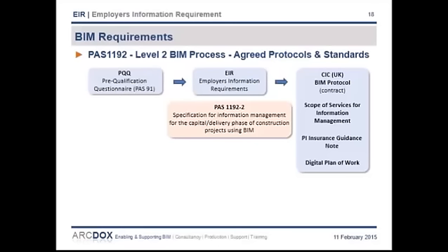The client will also want to make sure that their teams are aware of the implications of BIM for PI insurance, and to provide absolute clarity and avoid misunderstanding, the client will have to set out their requirements in a digital plan of work, which is basically a responsibility matrix that sets out who will create what information at each stage, to what level of detail and what level of information, and how the digital data will be coded and structured and classified and delivered as data drops. So this is currently quite an onerous task, but hopefully this will be made easier by the BIM toolkit that the NBS are currently developing, which is due to be released this year.